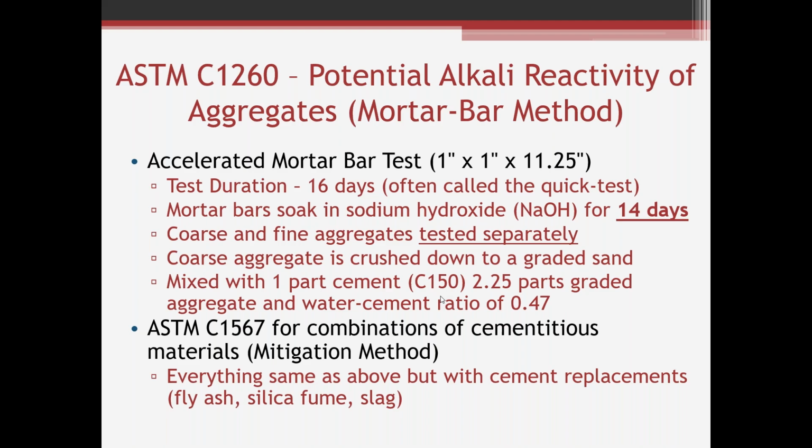And the test evaluates coarse and fine aggregates separately. So if you've got a fine aggregate that you want tested, we mix it up with 1 part cement and 2 1/4 parts graded aggregate. So we grade the fine aggregate, so the gradation is the same for every sample.